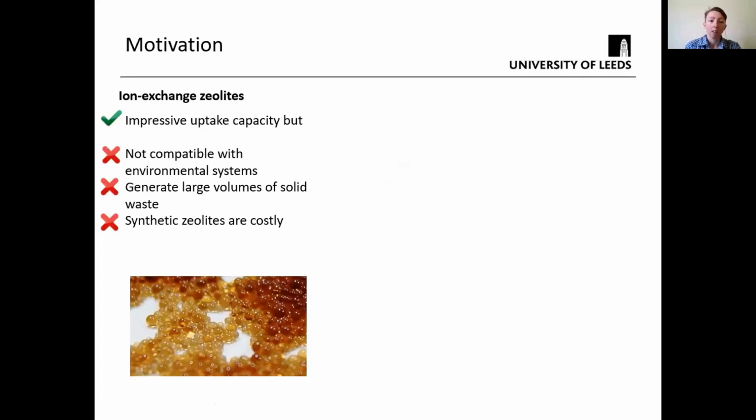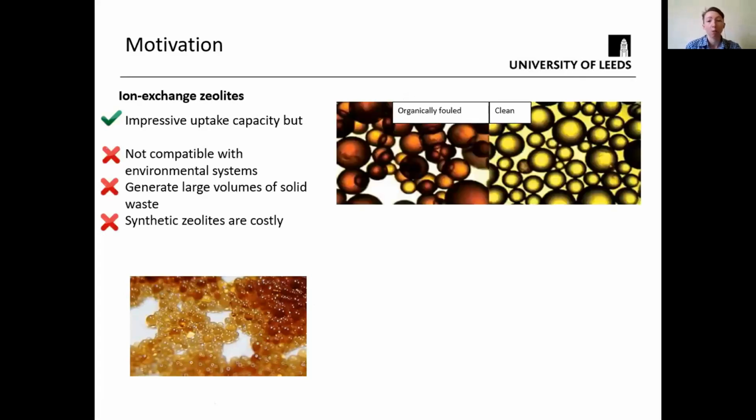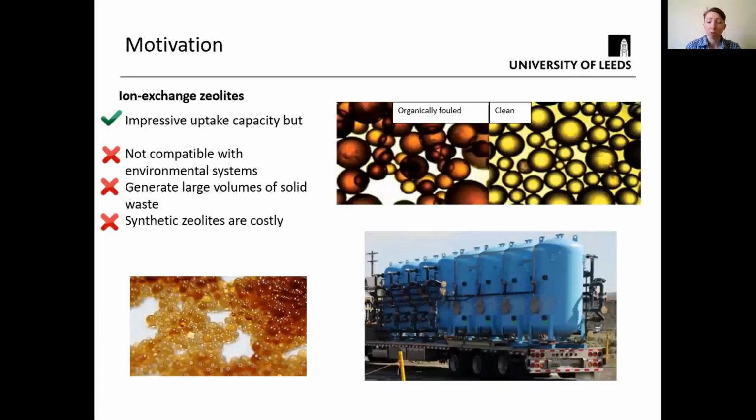For example, they're not compatible with environmental systems, so they are fouled by organics quite rapidly. They generate large volumes of waste as well, which may not seem like an enormous deal, but when you consider the cost of radiological shielding and long-term geological disposal of radioactive waste, costs spiral quickly. And finally, the zeolites themselves can be very costly.